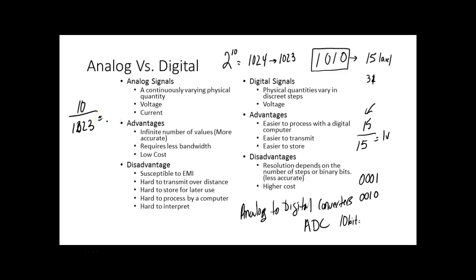What would be the transfer function? We can say we'll probably go a little further than that. Like 9.7 millivolts, right? Per count. So now my resolution goes way up, right? You understand that? So now I can represent temperatures.